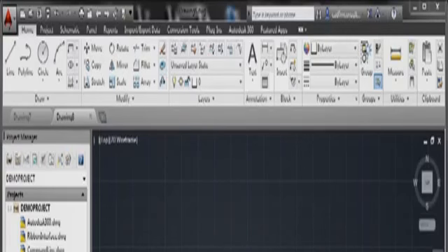We'll look at dynamic input later on in the course, and you now get a prompt that will follow you around with the crosshair. In the input box, type 1 and press enter. Now, in AutoCAD Electrical, we have just flicked a switch, if you'll pardon the pun. We've actually switched on the startup dialog box. So what we'll do in the next video is we'll have a look at how that startup dialog box works. At the moment though, we've got it all switched on and we're ready to go.